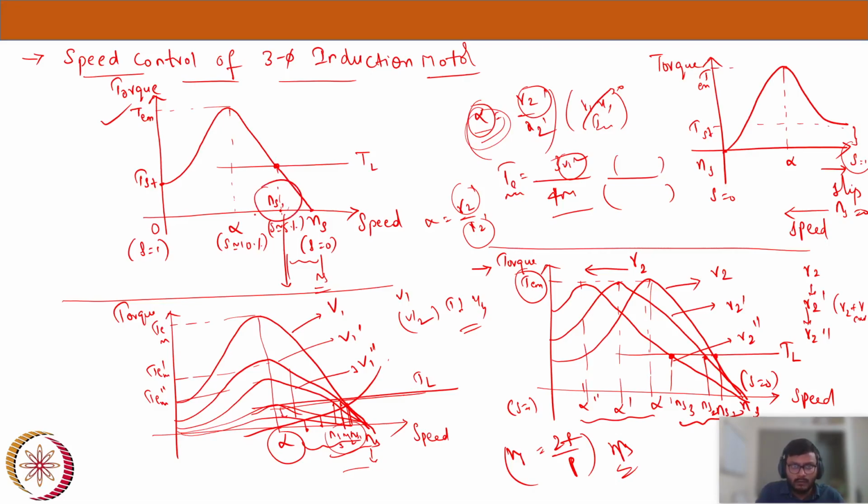So it will be somewhere around 5% slip. If it is 3% slip, it will be close to synchronous speed. Everything is fixed now. So that's why previously people used to consider our induction machine as a constant speed motor, because there is no point in getting speed control. So let's not use our induction motor for speed control at all.